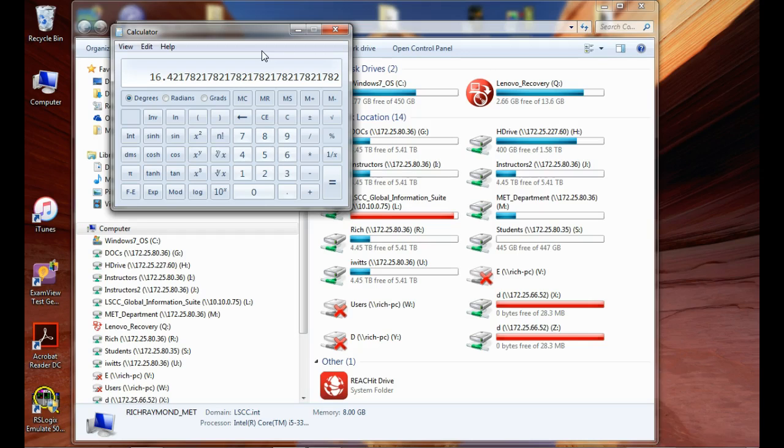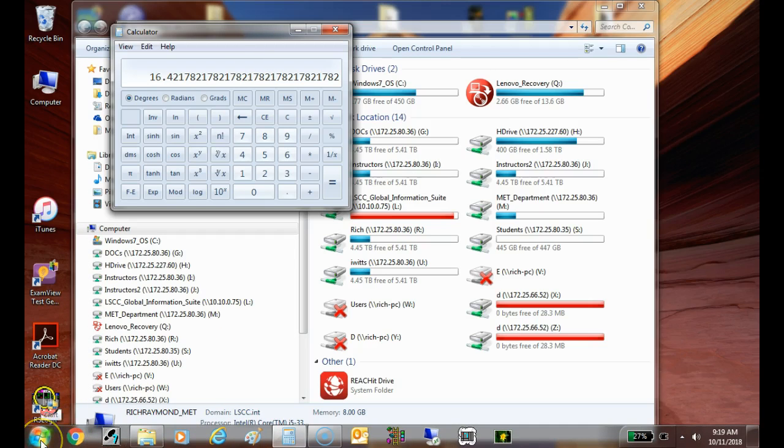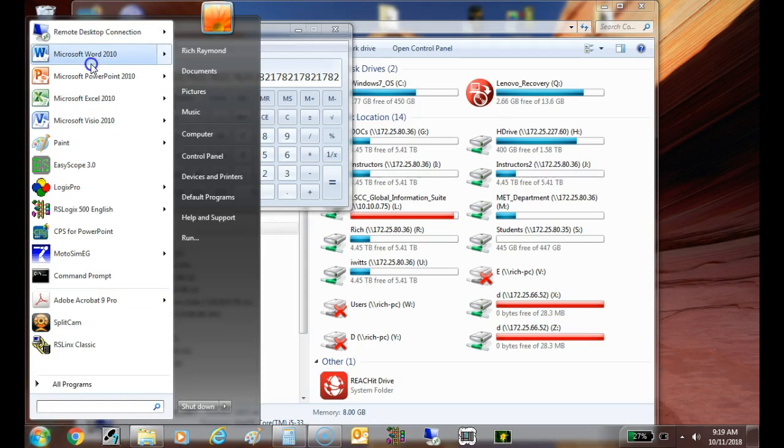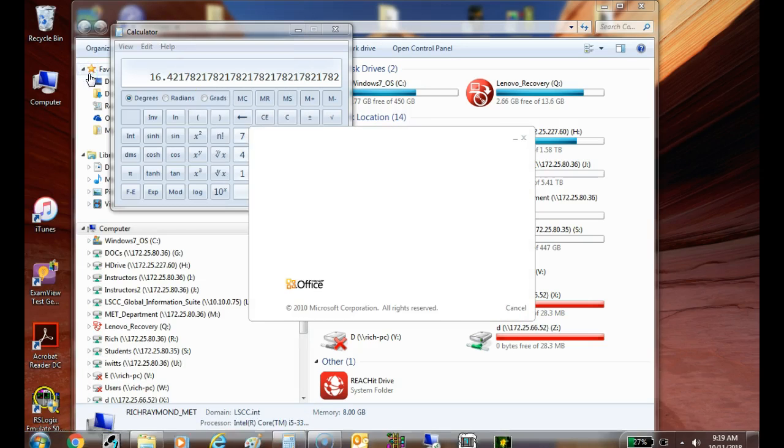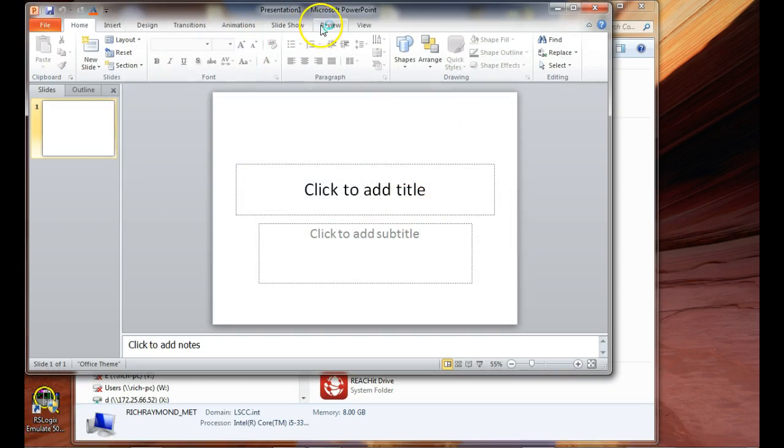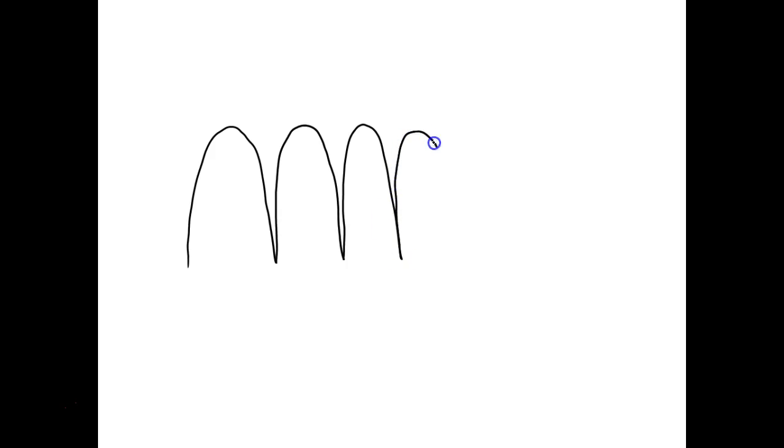But what we got to understand is that that 16 volts is peak, right? Y'all understand that? So what we're going to do, of course, is we got to come over here and say, okay, what did we say? I had 16 point what? Okay, so 16.4 or 16 volts. But if I full wave rectify, I got this, right? You understand? My regulator won't handle that. So what are we going to do with it?